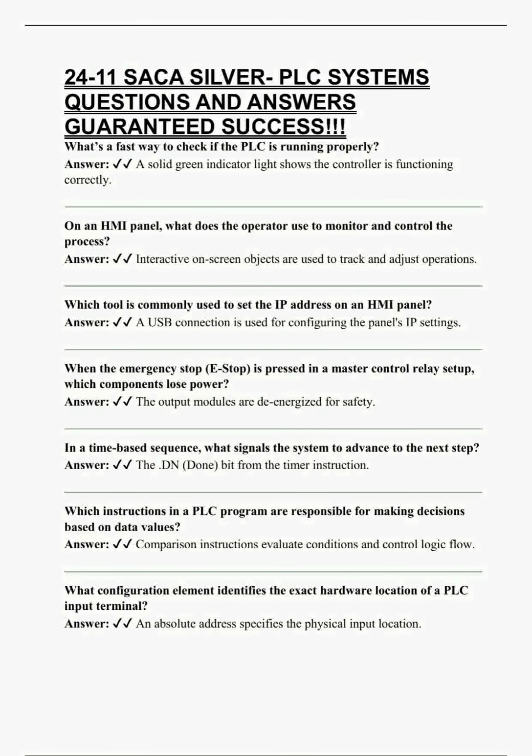In a time-based sequence, what signals the system to advance to the next step? Answer: the done bit from the timer instruction. Which instructions in a PLC program are responsible for making decisions based on data values? Answer: comparison instructions evaluate conditions and control logic flow.